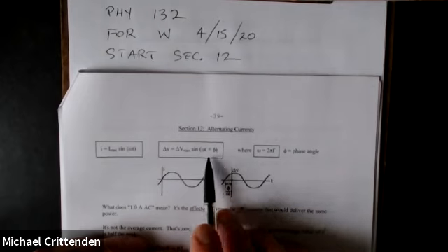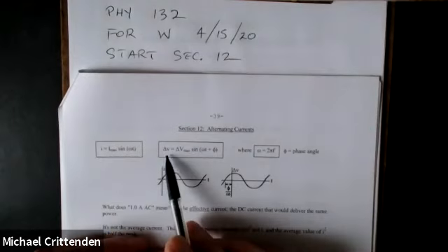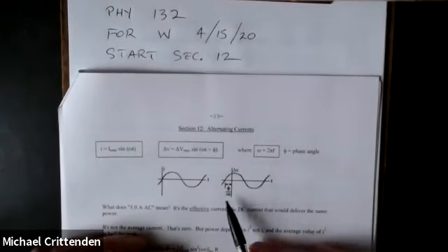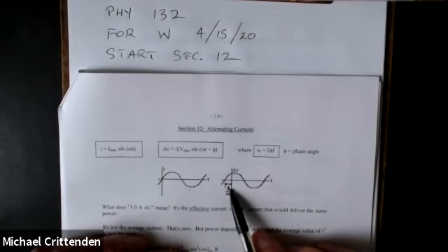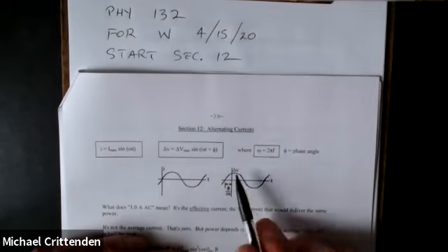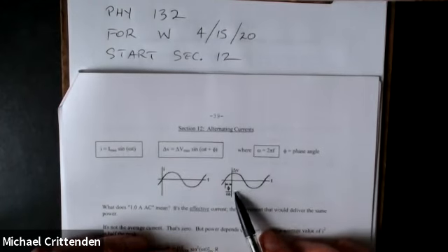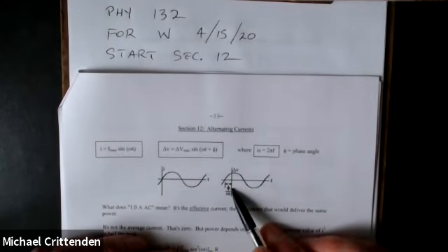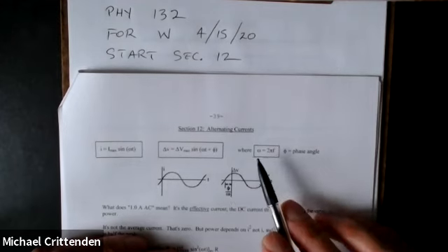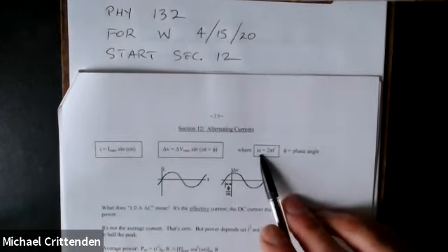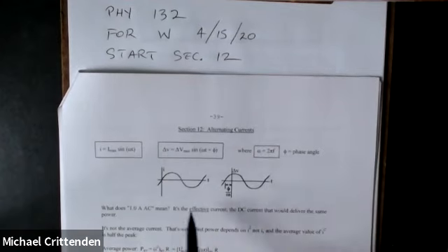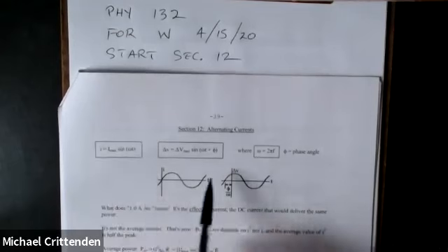That's the phase difference between the amps and the volts. So one curve would be shifted relative to the other, the volts shifted relative to the amps by an amount that depends on the phase angle, like that. And omega, of course, equals 2 pi f, like we've encountered more than once before. So these will be the general equations for how current and voltage vary with time.